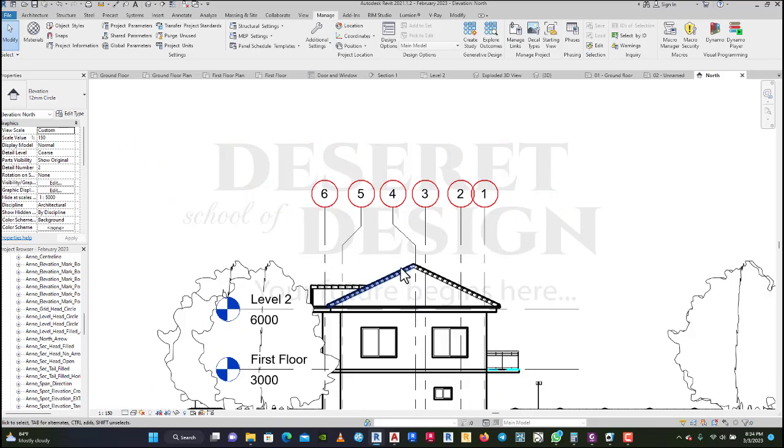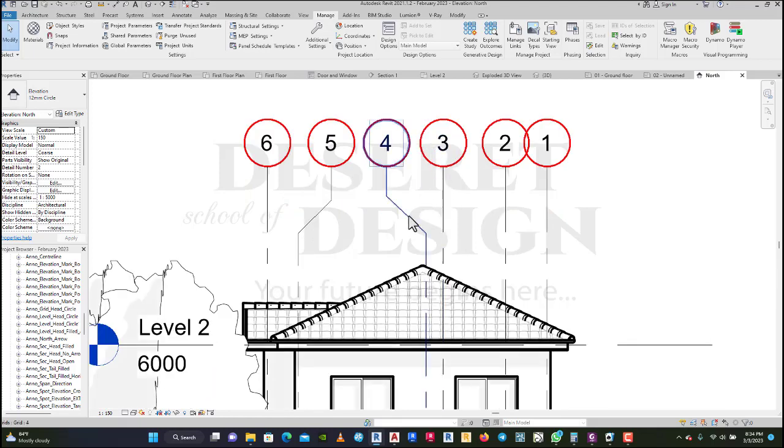Okay, so this is the way to also edit the grade line. Most of the times when you do your scaling, it will not go with it. It will not also scale down. So after scaling, you need to go and scale up the grade line parameter itself. Okay, so now, what are we looking at?